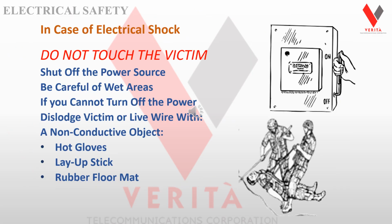Now, if somebody is in contact with an energized source, do not touch the victim until the power source has been shut off. And also be careful of wet areas. Water is going to be a good conductor for that current. Now, if you can't turn the power off, you can try to dislodge the victim or the live wire with a non-conductive object. Your hot gloves, a layup stick, a rubber floor mat will help.